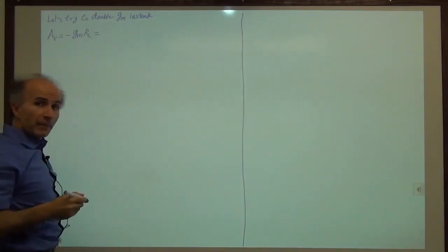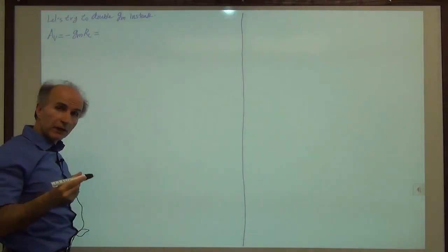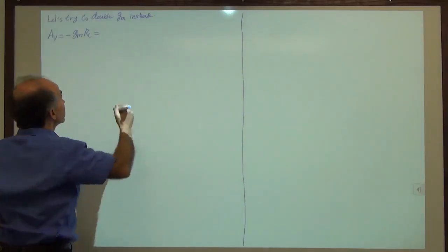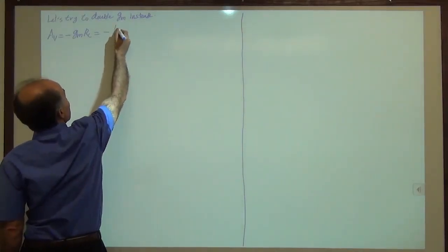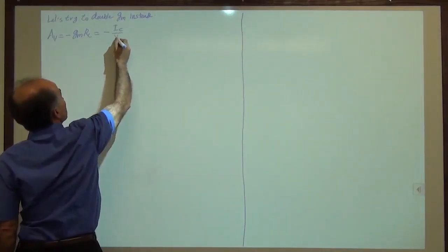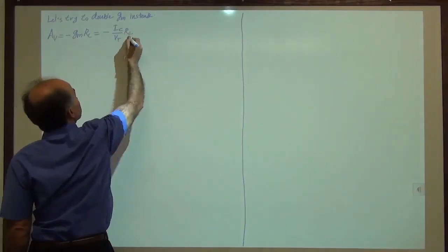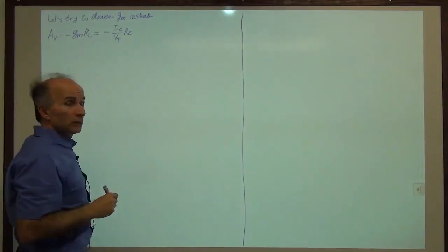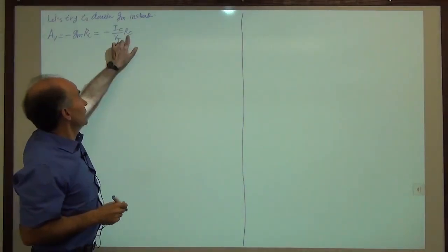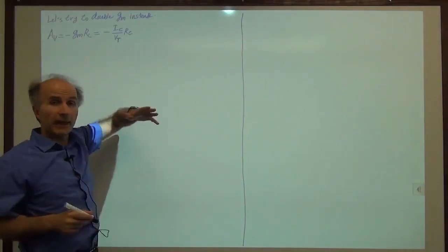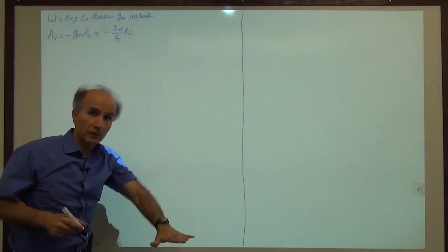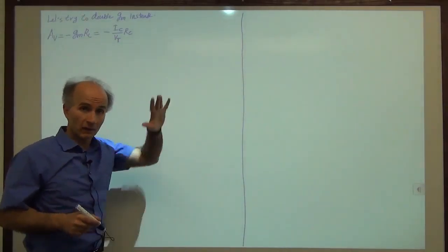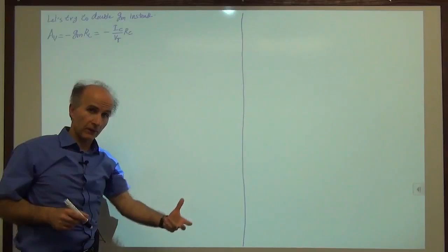And we know that GM is given by the collector bias current divided by VT. So we have minus IC over VT times RC. And we concluded that if we just go ahead and double RC to double our gain, something bad happens. The collector bias voltage, without any signals, falls so much the device goes into saturation.